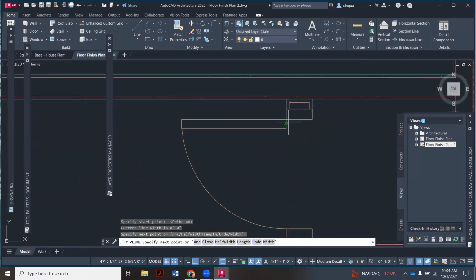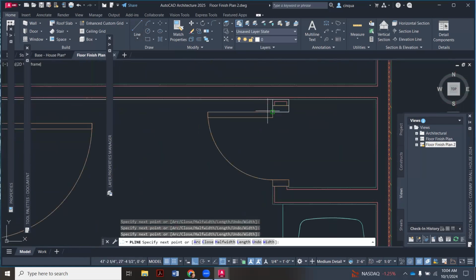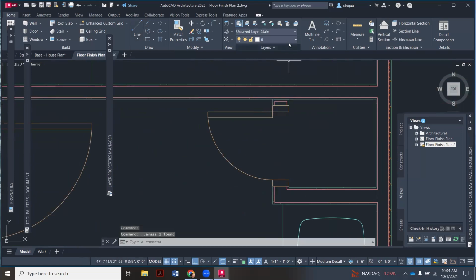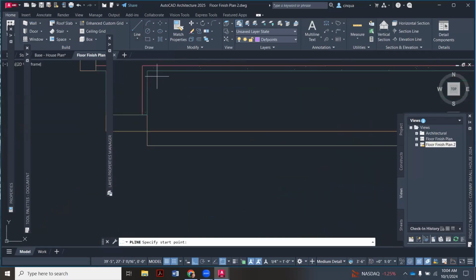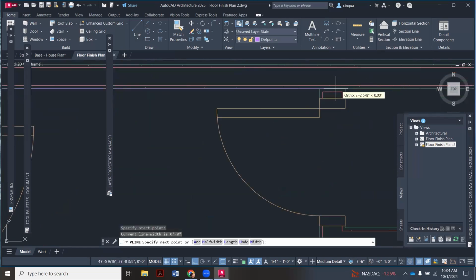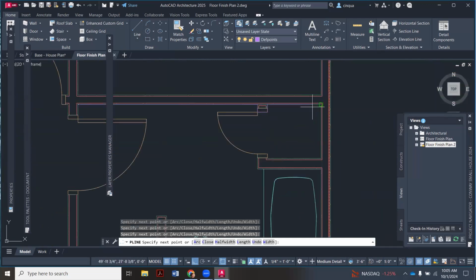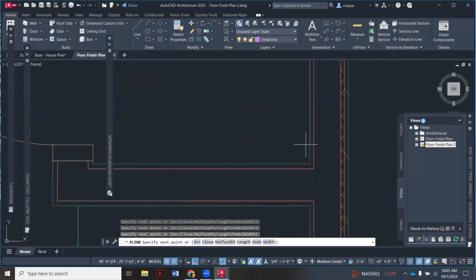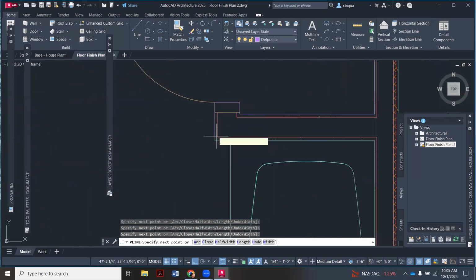Now, in class, we talked about we're not going to outline all the doors. That's a bit of an older style when you would hand draft this. Here in CAD, oops, as I'm talking, I realize I'm not on the right layer. So hold on, let's get on def point. So here in CAD, what happens is if we were to outline all of those sections, let me go back to polyline, make sure I got that. It kind of blows the mind of the computer trying to hatch going around these shapes. Because see how if we went around it, we kind of come back to this point. That makes it hard for the computer to basically paint in the hatch pattern. So we're going to, for now, go around and over the doors. You can kind of crop them out later, and I'll show you how to do that in a minute.